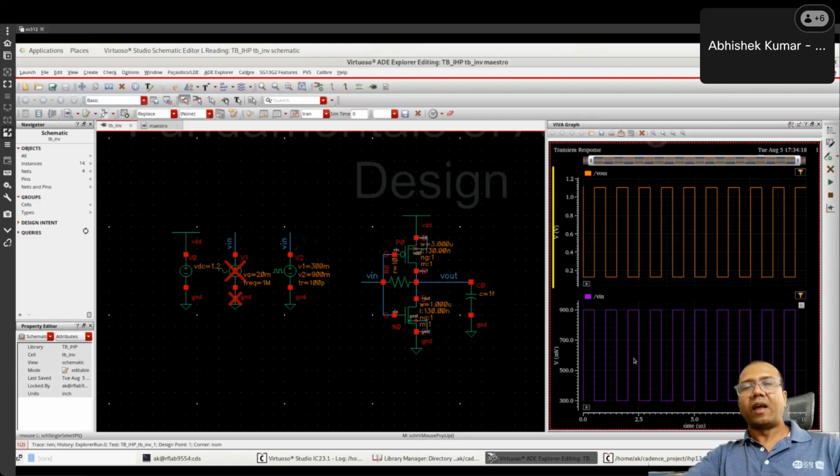So when we are having this kind of digital signals, we can design circuits which will process these digital signals with the help of very simple switches. For example, in this case, this NMOS and PMOS are actually acting like switches. What these switches will do is they can buffer these digital signals to an output. In addition to that, here we also do inversion. So we increase the swing of the input to a higher swing. Here you can see now the swing is increased, and now we are going from close to 0 volts to close to 1.1 volts. And it is also doing the inversion operation.